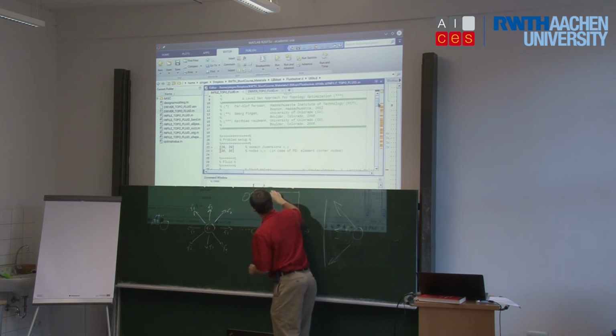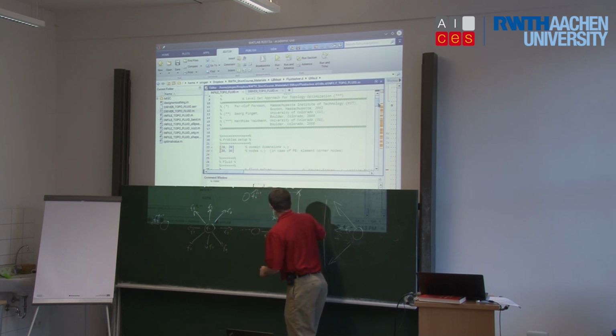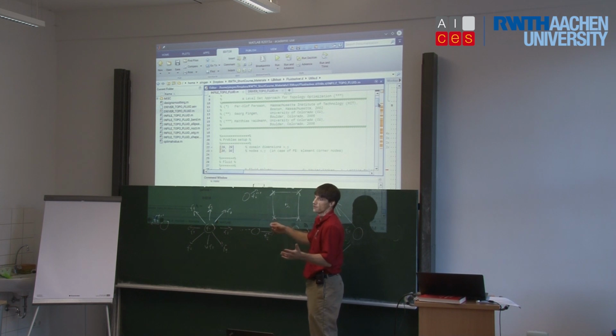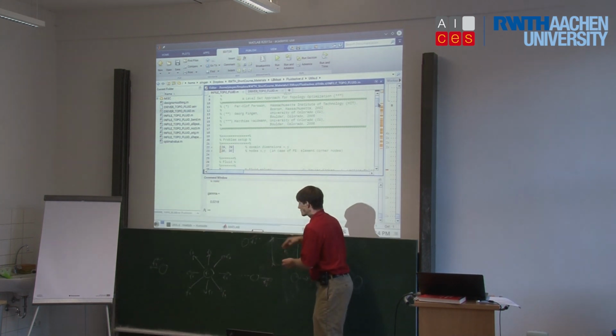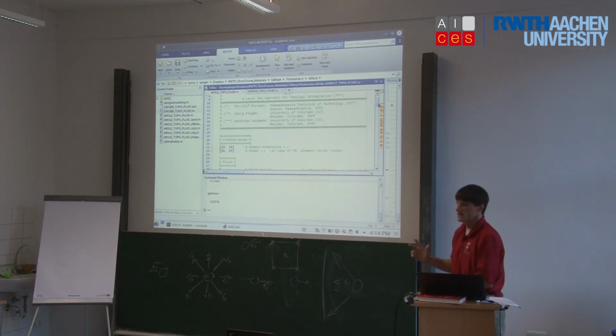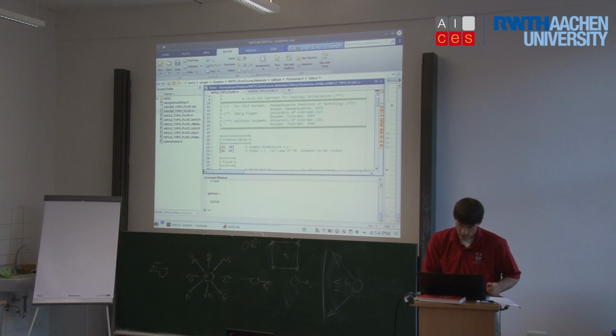A grid like this, I have nodes, lattice Boltzmann points right here, and I have design variables right there. At each lattice Boltzmann point, I'm actually taking the average of the 4 neighboring design variables. The reason for that is so that the result gets smoothed a little bit instead of having very jumpy points. But you could do it without this averaging as well.